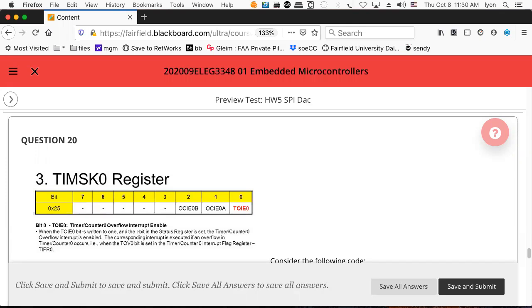There's a piece of hardware which can run at the same speed as the CPU clock. It can run at a maximum of 16 megahertz. And what you can do is have it generate an interrupt. When the interrupt comes in, you can service that interrupt. It's sort of an interesting internal clock that you can essentially set to an arbitrary value. When it reaches the overflow, it interrupts, and then you can service the interrupt and reset the timer and set it so that it'll interrupt again.